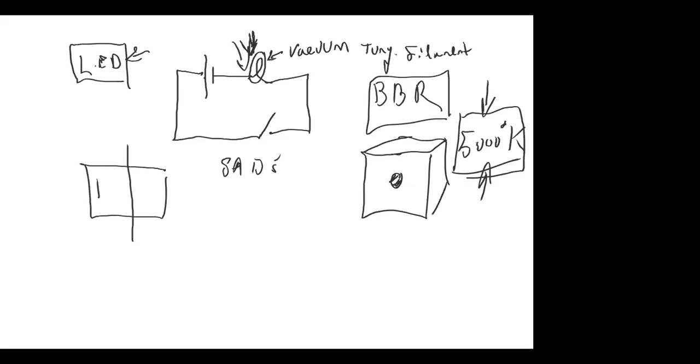And what you do is you get two pieces of silicon. Each one is doped. That is to say, one has got an impurity added to it, which has an excess of electrons, and another one has an impurity added to it, which has a deficiency of electrons. The one with the deficiency is known as p-type, and the one with the excess is known as n-type. And then there's a barrier between these two, which we call a junction.